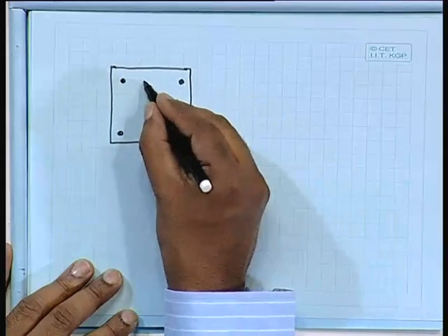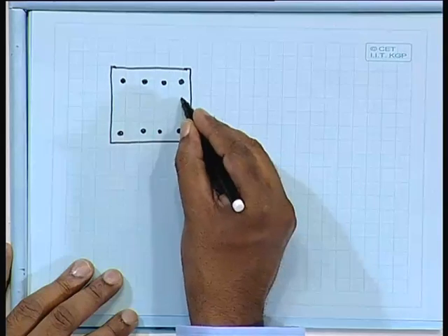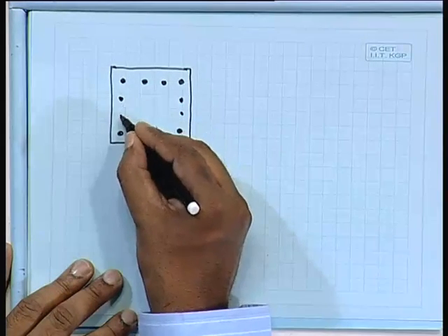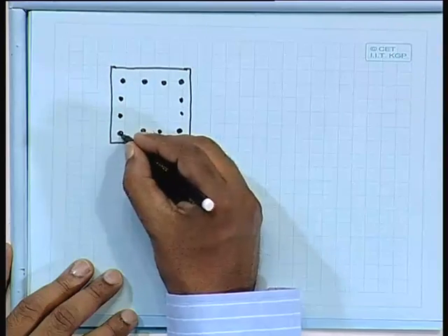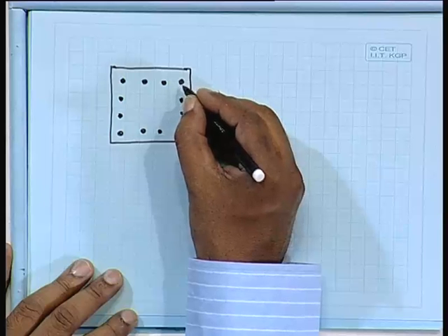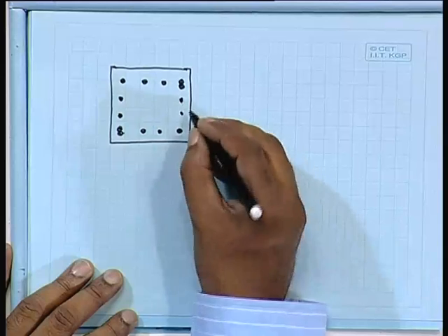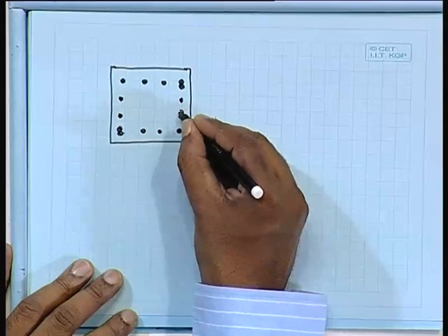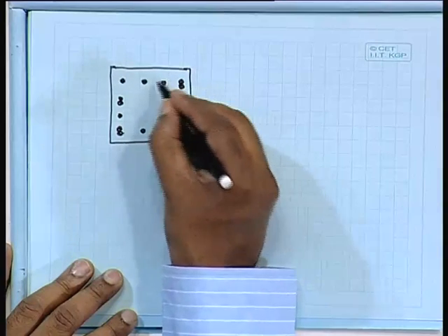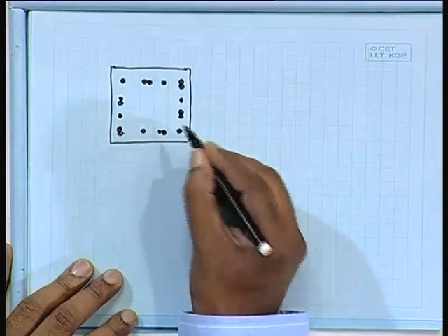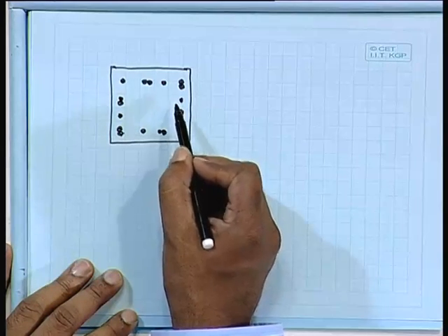So, what we shall do, we can start even if I take 50% at a particular section. Let us say we have this bar and this bar. I can provide 1 bar here, then 1 bar here. Similarly, I can have 1 bar here, 1 bar here, like that it will go. Similarly, 1 bar here and 1 bar here. That means in a particular section, because these bars are lapped, you are giving the lapping to these bars.